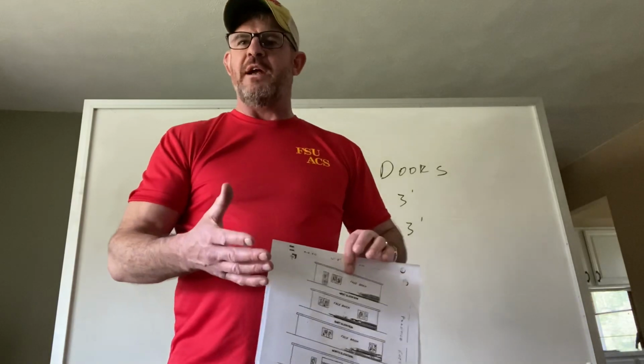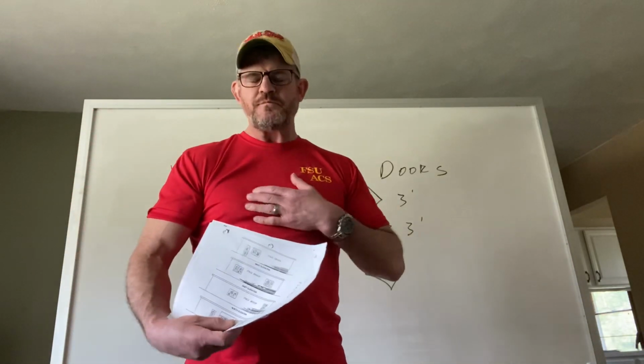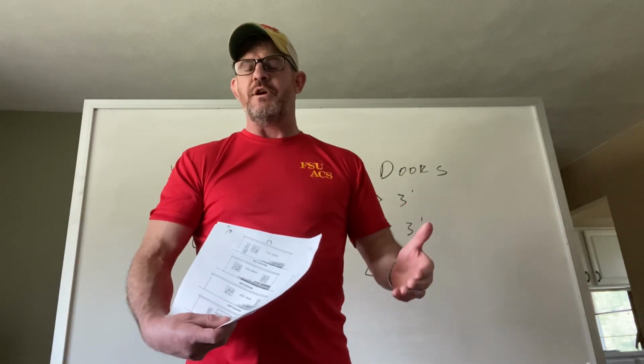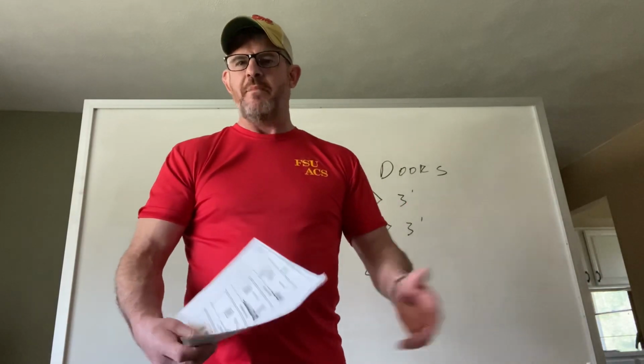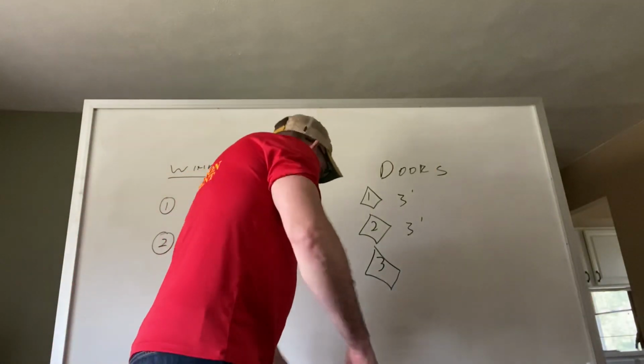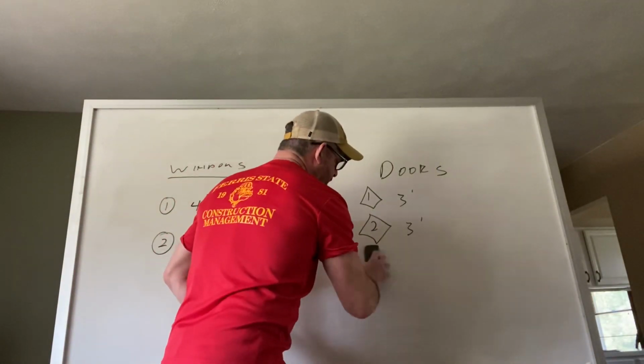As long as I have the correct number of block, the correct number of pieces of material that are ordered and brought to the job site, I'm going to be okay. But the point is that before I ever get there, I have to have the ability to set up and perform that math problem. So in our case, I'm going to decide that we're not going to determine the lintel for door number 3, knowing that I'm going to determine that number of block when I get to my bond beam, and we will be there shortly.